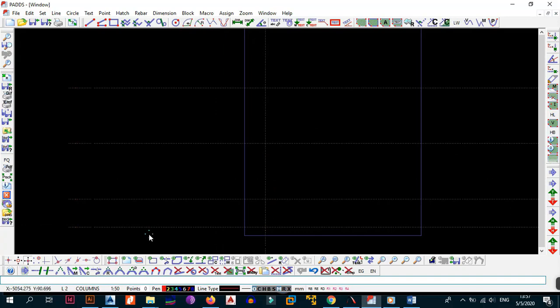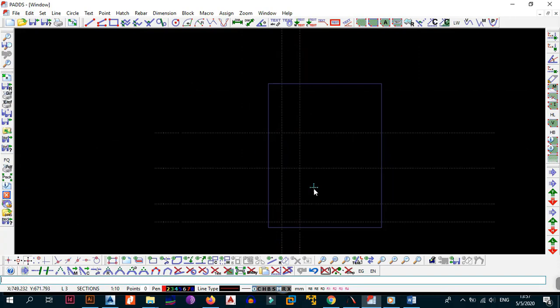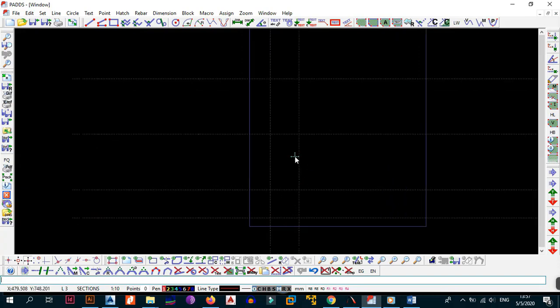Then the next thing you want to do is change the layer now to 3. Then LP this line by 300. Once you LP it by that, you're good to go. Doesn't look too bad for me. That is actually okay, quite fine.